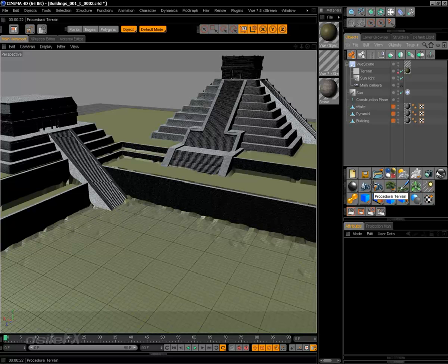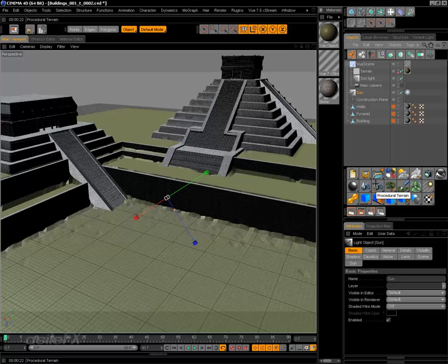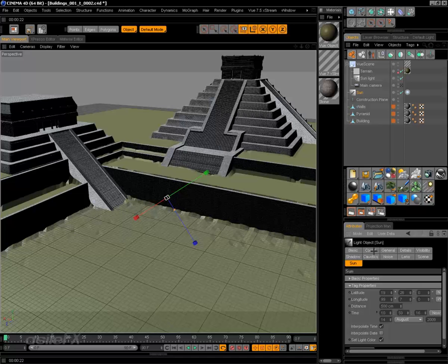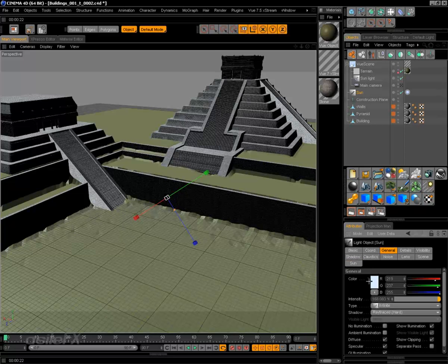And this method works best when you're using the view sunlight rather than the sunlight we have. The exact match is not carried out completely into view, it's mainly a placement and then an editing of the main sunlight. So what we do need to do is copy a few settings over. What we need to do is grab the color, so we can go to the General tab and we can see the color that we currently have. And I want to move that color over to the view sunlight. So we'll just need to remember these values for the RGB.